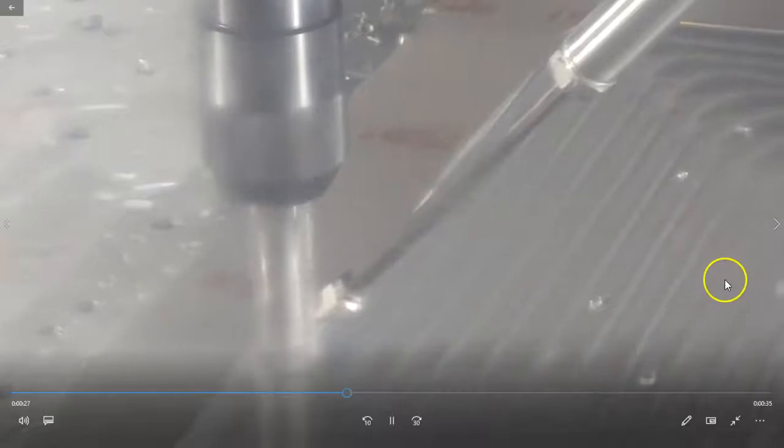just machining the material. So on this side there are 2 pins and a couple pieces of brass for this material to bank up on. And on the other side are the downforce clamps that put a little, and I'm relying on the weight of the material and the little bit of pressure from those clamps and pins to hold this in place. So I believe it said 2200 RPM at 34 inches a minute.